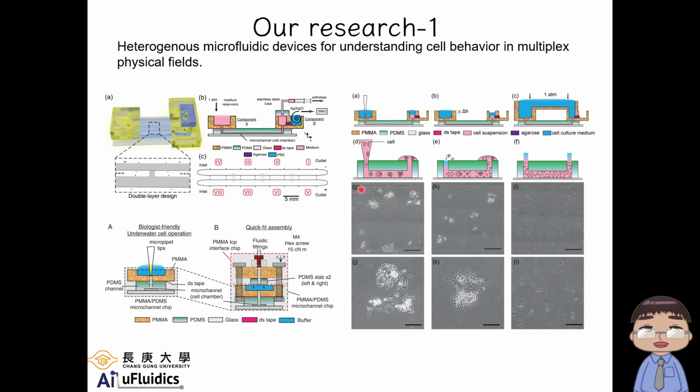Now, in addition, understanding the thermodynamics and fundamental fluid dynamics inside microfluidic systems help us a lot, and this is something we can also realize by heterogeneous microfluidic devices, where if it were a conventional typical microfluidic device, if there's any hydrostatic pressure differences, we inevitably have secondary flow that could displace the cells and then cause them to aggregate. Now, this will be a disaster for analysis as well as cell experiments, where we cannot get single cell behaviors, nor could we analyze this reliably.